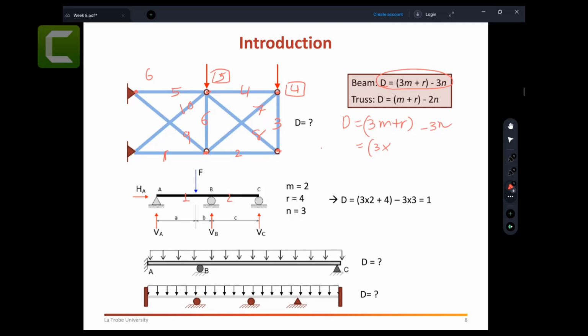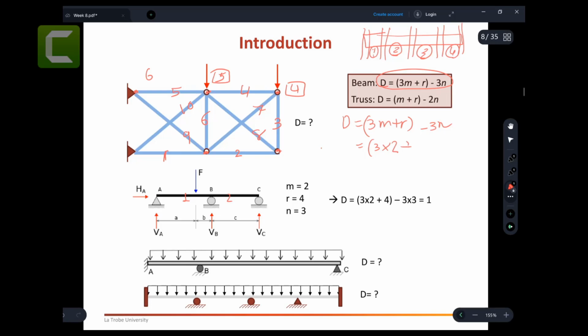Now, when you have a beam like this, and these are the columns, this is one member, this is the second member, third member, and fourth member. So it's one beam, but within that one beam you have members. You can easily recognize that between the two supports you have one member and a second member. So you have two members. How many reaction forces? You have one reaction force, two, 3 and 4. So you have 4 reaction forces.